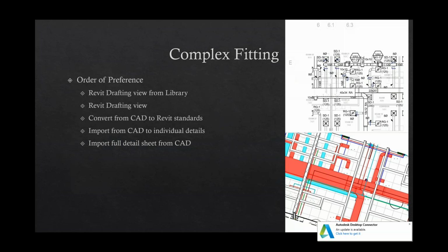For the plan view itself, there are times where the Revit Imperial Library might not have everything you're looking for. There might be a couple of instances where you can fake it using some of the fittings at your disposal. Again, that can only be done if you know you're not going for analysis and are willing to ditch the full connectivity. But the library is pretty good. Most of what you need is in there. But where you absolutely need to, you can bring things together and make it look pretty close to it.